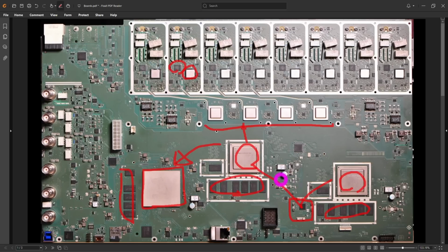Now this is a digital system at the end of the day, so the sensitivity to jitter in terms of achieving signal to quantization noise ratio is not the same as the clock that's provided to data converters, but nonetheless everything needs to remain synchronous, and I'm sure there is a way to synchronize the main PLL for the data converters and this entire system. And of course this FPGA is also going to require a clock of its own, and that's why the multiple clock outputs of this are most likely helpful, creating a clocking system for the entire digital backend over here.